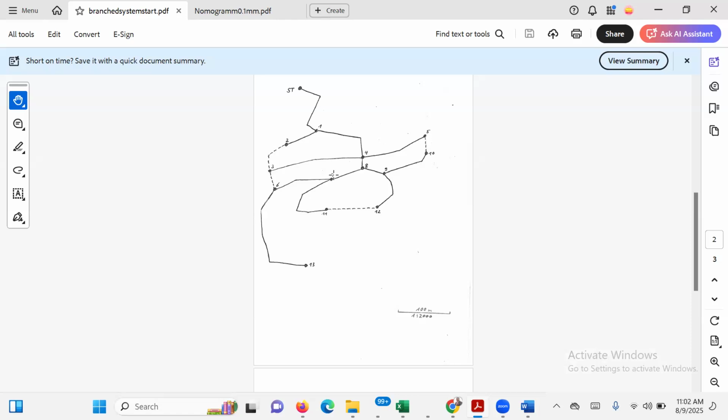That becomes the sink, or its own base demand. That's what we call it, its own base demand. Then I'll now add it to the secondary demand, which is node 11 and node 6. Because when node 7 services the houses along these places, it will still service node 11 and node 6, because water is flowing upstream, because it is upstream of the other 2 nodes.